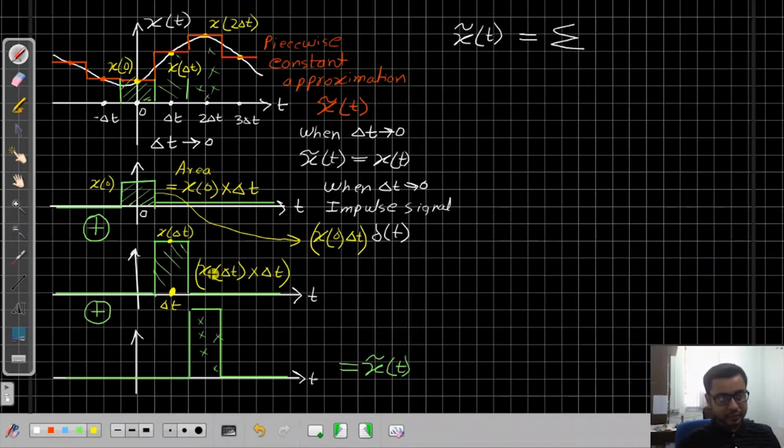So this signal can be written as this number multiplied by a delta function, not delta t, rather it should be delta of t minus this del t. Okay, do not confuse this capital and small delta. This should be t minus del t, because when you shrink this into a narrow pulse, that pulse is going to occur at this point.